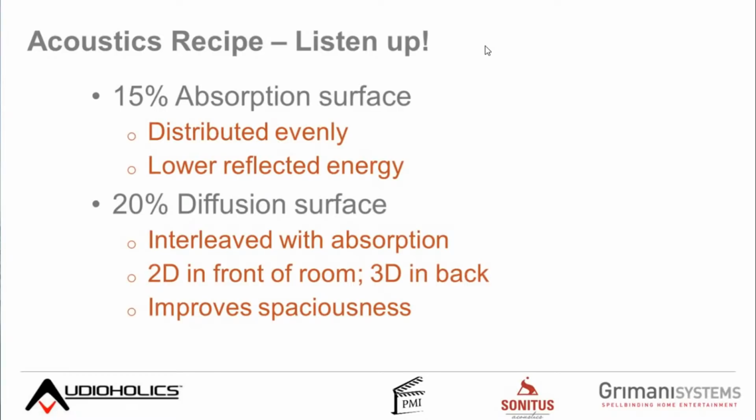Well, if you put them all above your head, you've added some absorption in the room, but you still have some echo. So usually we tend to put them about a minimum of 12 inches below your ear height, which is typically 39 or 40 inches off the floor. So minimum of 12 inches, sometimes 18 or 20 inches. And then you go up about, again, another 1.5 feet or 2 feet.